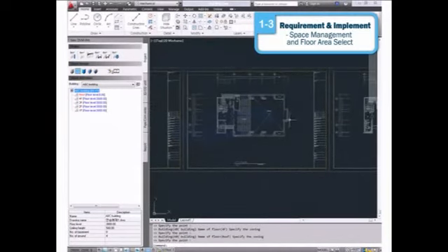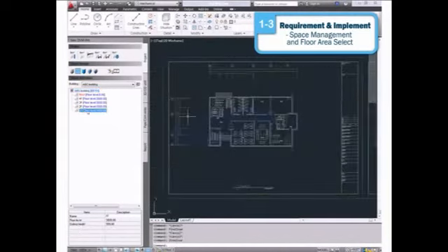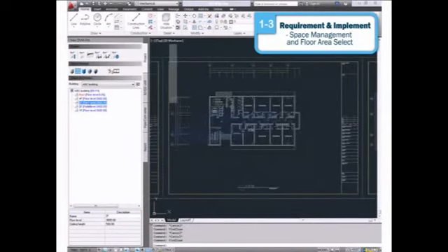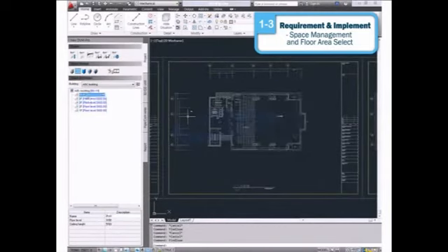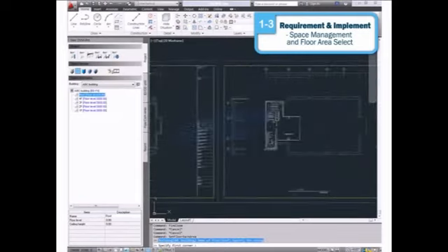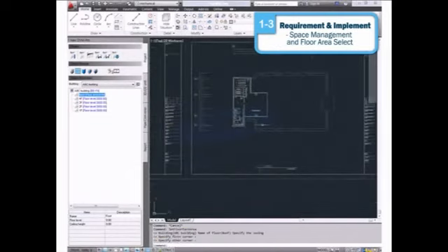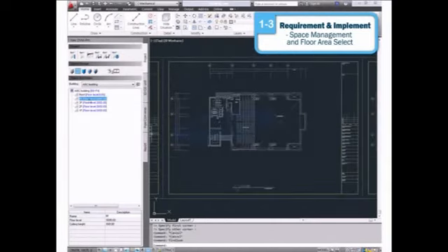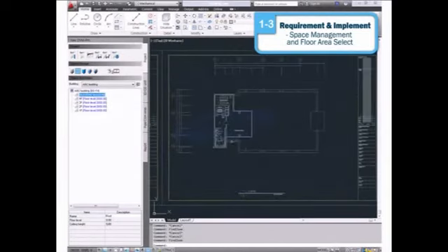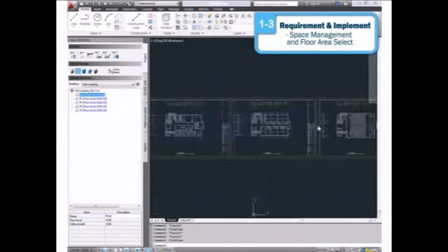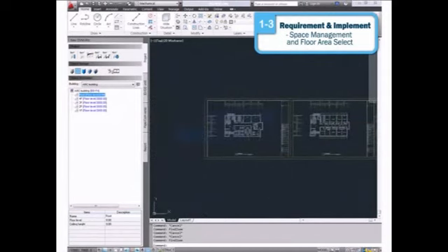Let us use the second floor area selection method for the roof, which is called floor area individual selection. Click Roof from the space information list, and click fourth Specify the Zone each floor icon on the Space Management section. Click top left corner of the floor plan for the roof, followed by clicking the bottom right corner to set the floor area selection. When you click icons on the DVM Pro, pay close attention to the commands that appear on the AutoCAD command display before using them.